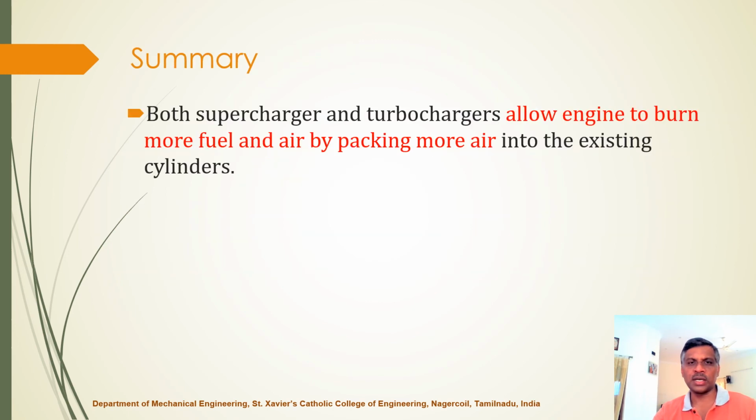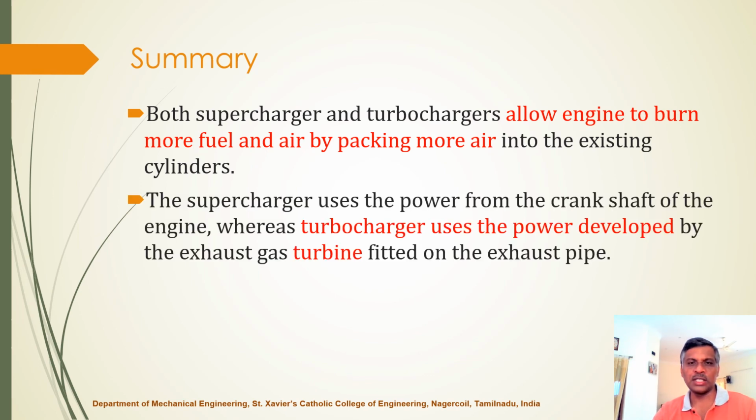So I'll just try to conclude. With the supercharger and turbocharger, the advantage is that more air is taken in, more fuel can be burned for the same existing cylinder capacity, and more power can be obtained. But the problem with the supercharger is that it consumes power from the crank, whereas the advantage of the turbocharger is that the power is developed by the waste exhaust gas. So that's an advantage.